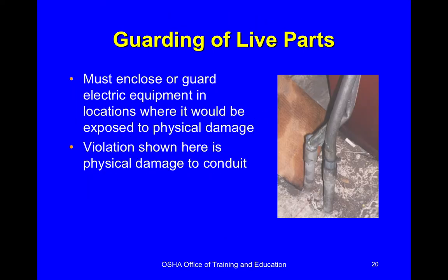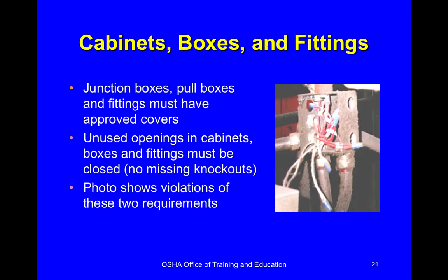This is a picture of conduit. It's where the wiring runs down through metal conduit. When you see physical damage like that, it's severed or bent, that could actually be cutting into the insulation of the wires inside, and those could actually be energized right now. Okay, that has to be taken care of.